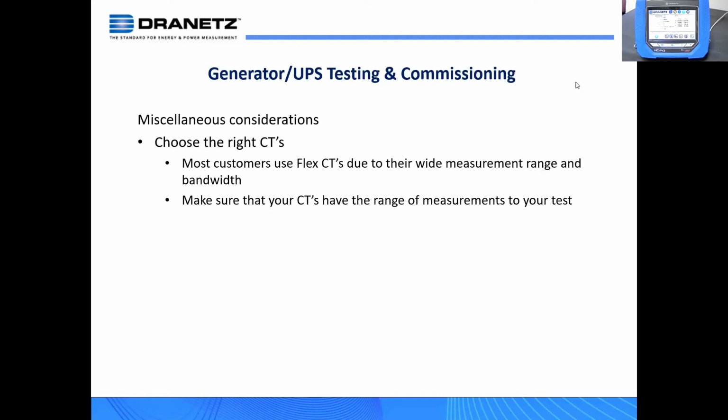But for the sake of this test, we're typically looking at the UPS output in a mission critical sort of application. And so they're looking at stepped and load testing on that UPS output. So we're measuring one three-phase source. When we talk about fixed systems or larger portable tests, oftentimes we have an instrument on the input of the UPS and an instrument on the output of the UPS.